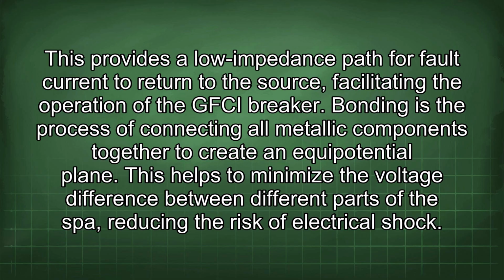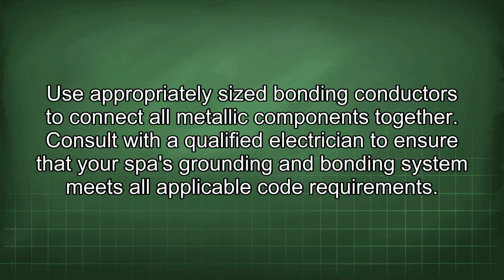This helps to minimize the voltage difference between different parts of the spa, reducing the risk of electrical shock. Use appropriately sized bonding conductors to connect all metallic components together. Consult with a qualified electrician to ensure that your spa's grounding and bonding system meets all applicable code requirements.